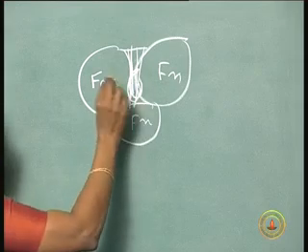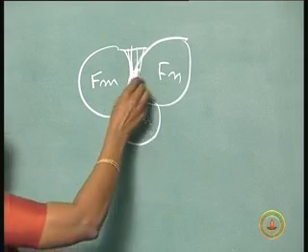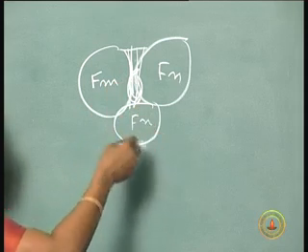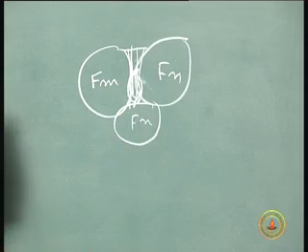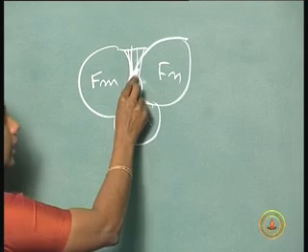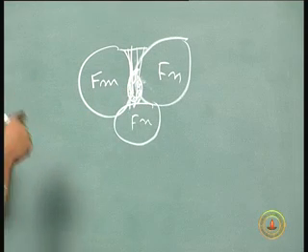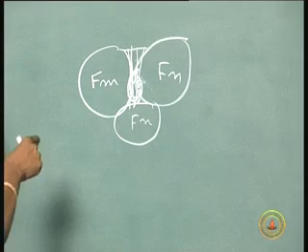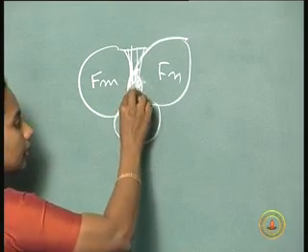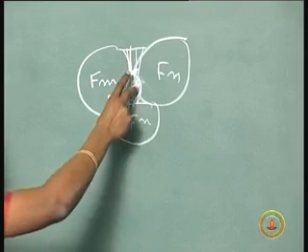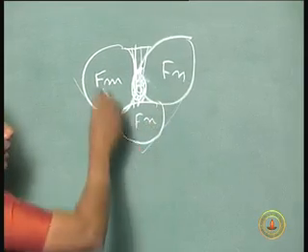But if your turbid particle is larger than this pore size between the filter media, it will get removed. And with respect to time, more and more particles will be coming and sitting here. So, the pore size will keep decreasing with respect to time, and more and more finer particles will be removed by the straining action. So, this is mechanical straining.